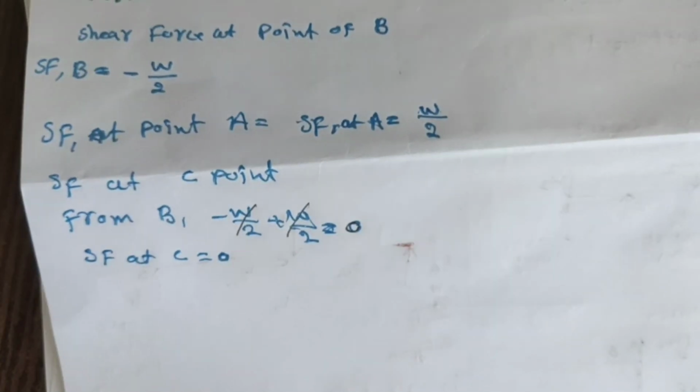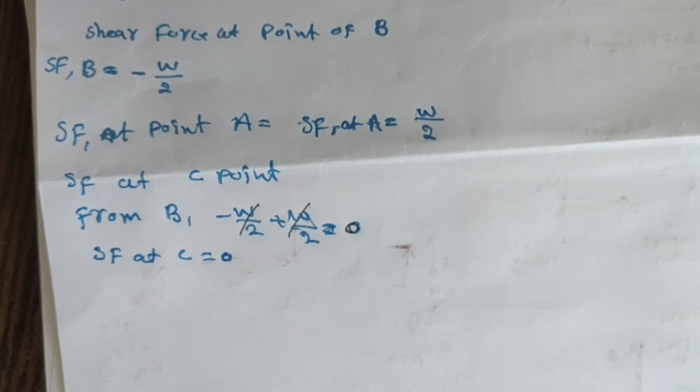Dear friends, please remember, when the load is acting at the exact point, the shear force will be 0, but the moment will be maximum. Please remember this point. When the shear force is 0, at that point the bending moment will be maximum. When the bending moment is 0, at that point the shear force will be maximum.